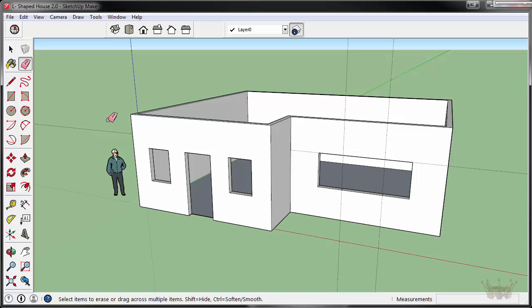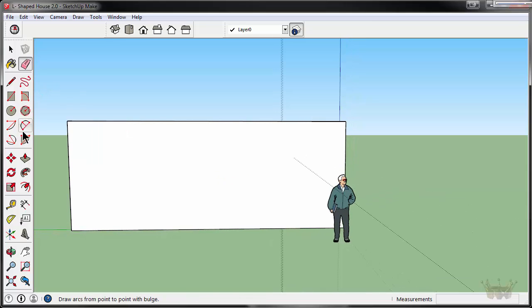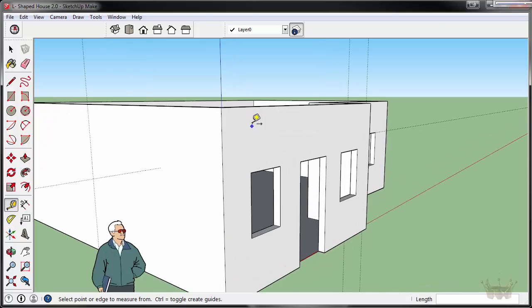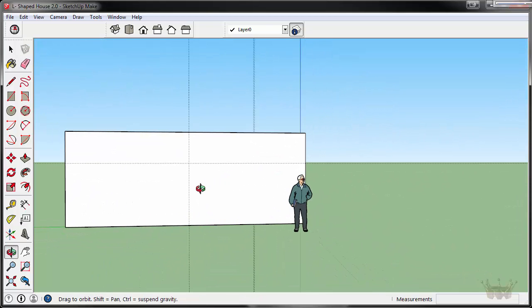With the front done, let's turn our attention to the left side of the house. We're going to create an opening here for a window, which, if you have time, you will build custom down the road. Let's keep our same heights, so I can come down from the top here, down from the top here, and that will mark the area of my drawing where my window will be centered.